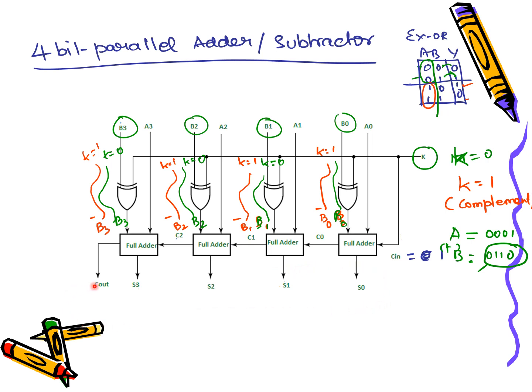So they thought, why can't we predict, depending on the input combination, as soon as we receive it, what the carry could be, whether the carry will be generated or not, whether it will propagate or not. So based on that, we can design a circuit. People designed it and came out successfully with the carry lookahead adder, which we call a fast adder.